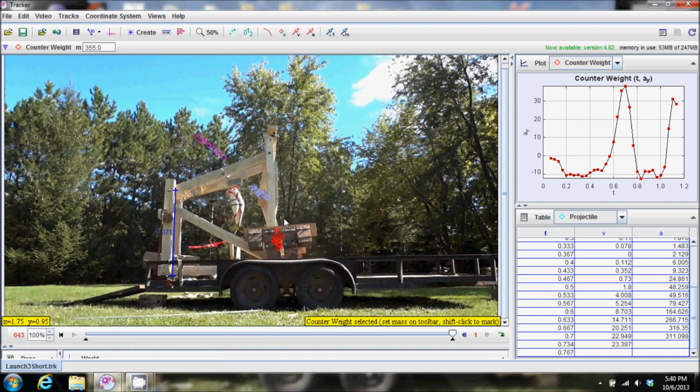Energy loss due to friction is also a big factor. All of my axles are just steel axles going through wood, so I don't have any bushings or bearings in those. Plus, some of my axles aren't very well aligned. I had some drilling inaccuracies or measuring inaccuracies when I made a couple of my axle holes, so I'm losing some there. The traditional Fiffer would have a pin in the back and an arm coming out that would guide the counterweight path. Instead, I've chosen to use a vertical guide similar to an F2K or a fat trebuchet.